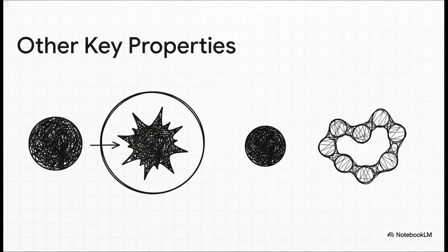Now, liquid droplets, they're easy. They're always spheres. But solid particles can be all sorts of weird, irregular shapes. So to make the math work, we often use something called an equivalent diameter. It's basically the diameter of a perfect sphere that would act the same way as our weirdly shaped particle. And density is similar. A solid chunk of material has its normal density, but a clumpy fume agglomerate has a much lower apparent density because of all that empty space between its branches.